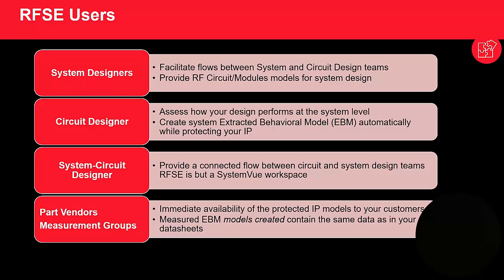For a circuit designer, it gives the capability to perform simulations that you may typically not be doing at the circuit level, and you could be doing RF system level simulations. And the second aspect that we talked about before is it creates an RF system level representation and captures it in an ADS MDIF file format called extracted behavioral model.